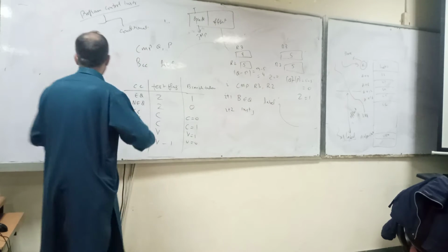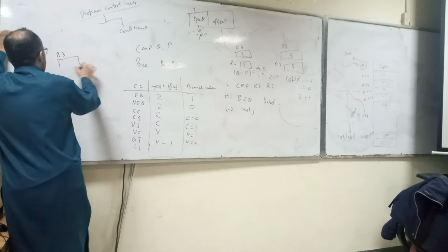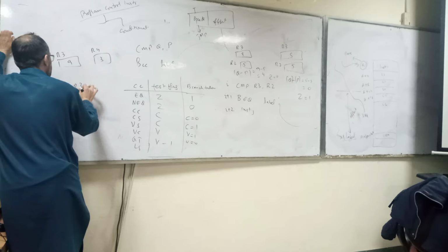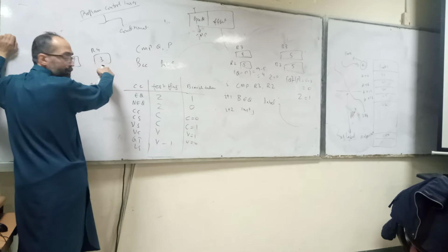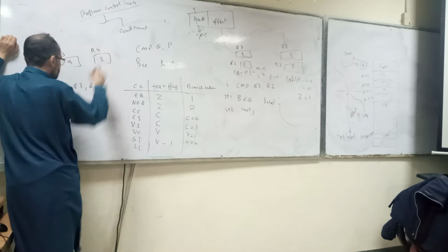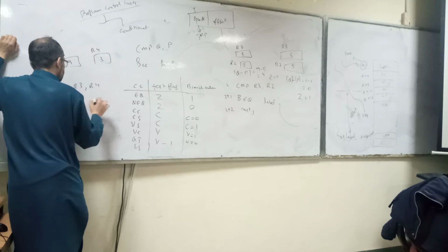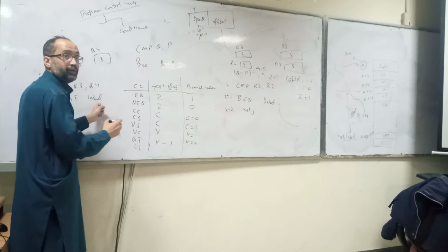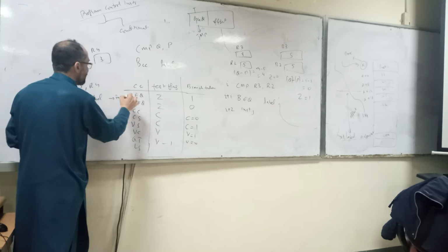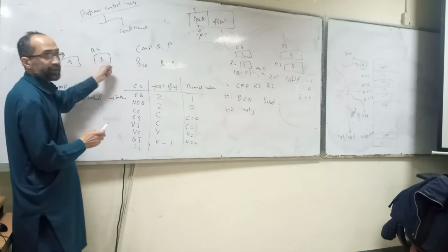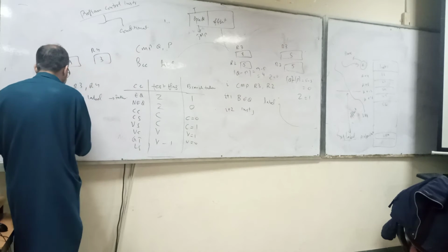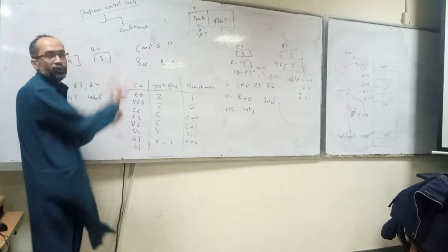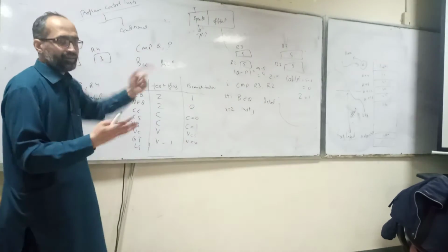So let's assume R3 is 9 and R4 is 3, and we say compare R3 and R4. It will compute Q minus P. R3 is greater than R4. BGT label: what will happen? Branch taken or not? Taken. Why taken? Because 9 is greater. And if we say BLS, not taken. The branch will not be taken. And if we exchange the values, then the same will be reversed.